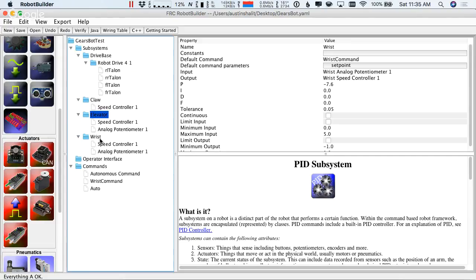So if you're giving this PID controller some input, it's able to calculate the short-term integral and the instantaneous derivative of the input, and then using some constants, you convert that into a motor output.